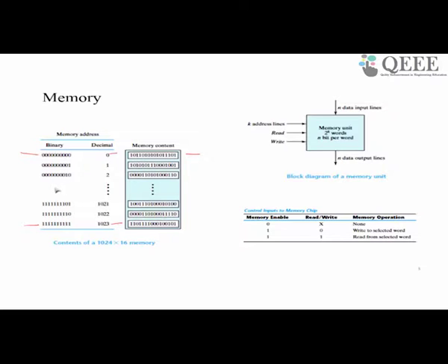Conceptually, how a memory works is, we can do two operations, one which we call reading, another called writing. So to begin with, we can write a content into a memory address location by providing the address and the corresponding data to be written and enabling the command. In this case it has to be a write command. If you do so and give some time for the memory to store the result, then the data will be written into that location.